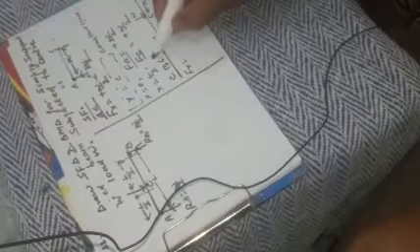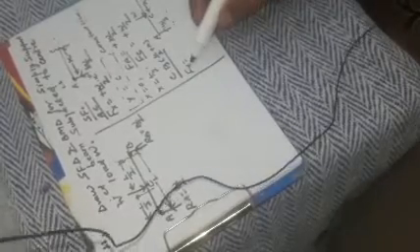So for this case, shear force will be Fx equal to upward forces. Total length of analysis for this case will be L by 2 plus X, right? L by 2 plus X. So Fx equal to W by 2 upward and W downward. So it is negative. The Fx will be minus W by 2. It is also X independent.